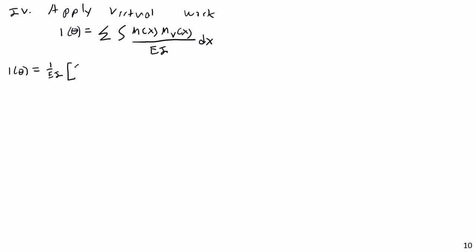So I'm going to set this up and show the integral, I'm going to put this AB here, and I'd be integrating from 0 to 15, and all I need then inside the integral are my moment expressions. So I would have 15x minus x squared over 2. That is the real moment expression, and then the virtual moment expression is 0 dx. But look at this. Anything times 0 is 0, so that goes away completely. We actually don't need to worry about the work on the column at all.